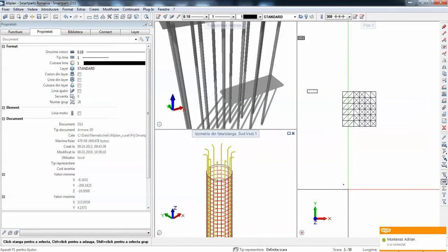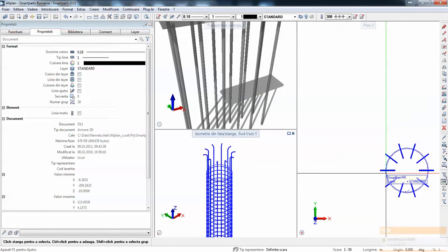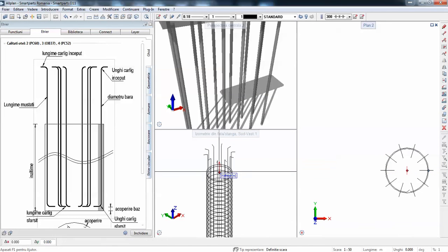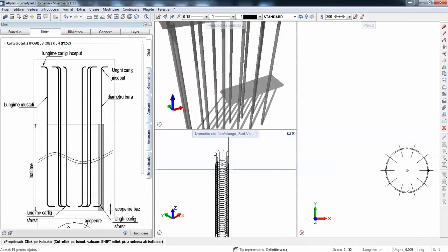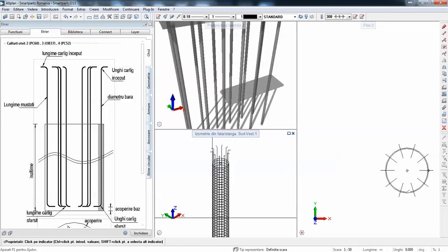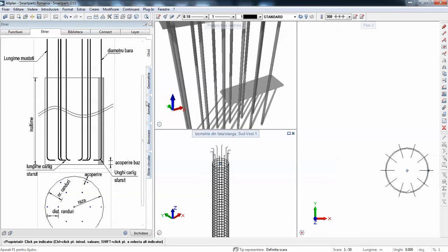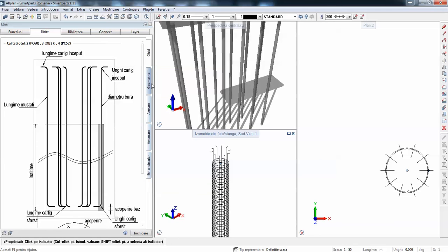So it is parametric, this one, also with handles. So I can do tricks like this on it. At that time they didn't develop the spiral reinforcement, but now also the spiral reinforcement is available in this coding. So this is a short graphical guide on what parameters, the concrete weight, the angles, radius, placements, whatever.